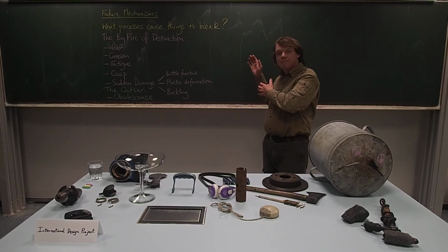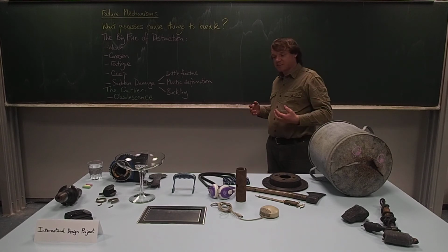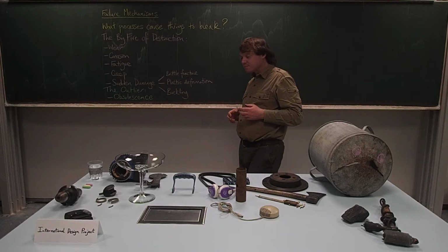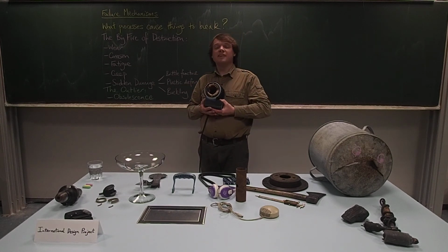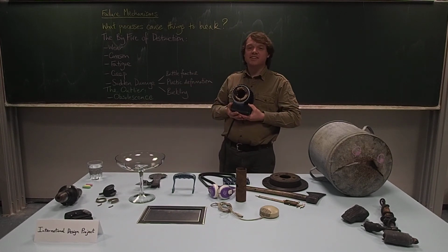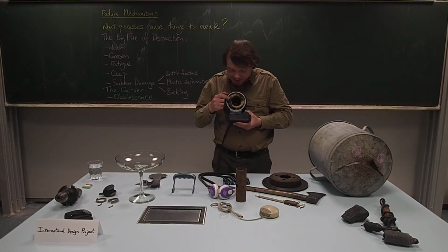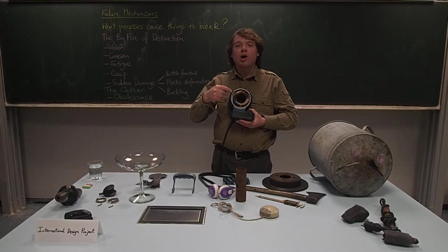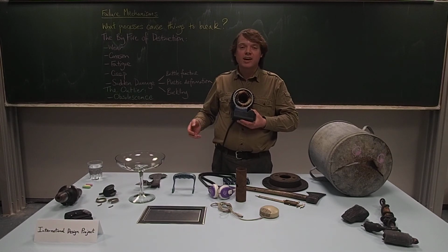Now, these failure mechanisms often happen in an interconnected succession. To give you some examples, if you think of an electric motor, like this one here, it is burnt out because the pump it was attached to seized, probably because the pump was blocked with sand or it was corroded, this kind of thing. And you can see here that the windings have turned black because the lacquer, the polymer insulation on the wire, has got too hot, to reach maybe 200, 300 centigrade.